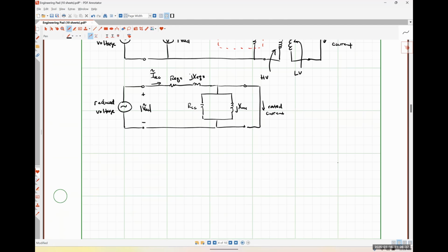The answer to that is the impedance of that shunt part or that parallel part are literally hundreds, if not thousands of times larger than the series part, it doesn't matter if they're referred to the primary side or the secondary side. So we know that almost no current is going to branch off and flow through them. So it really doesn't matter which side we put them on.